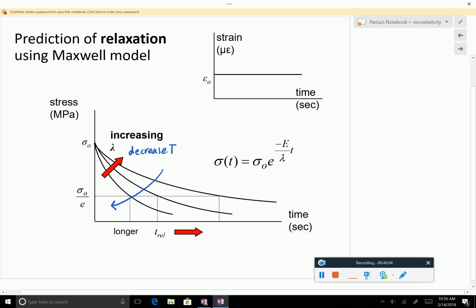If I'm increasing the temperature, the curves go inward. They are flowing faster, everything happens faster. So the stress goes back to zero faster. It makes sense, but the equations also support that. If you have here a larger number, it goes towards zero faster. It's a negative exponential.